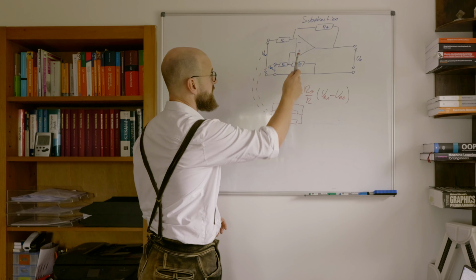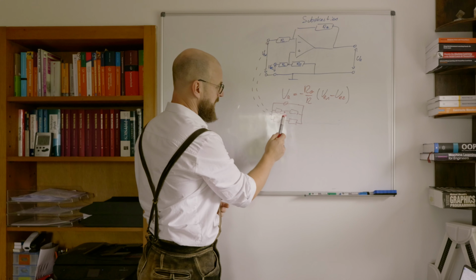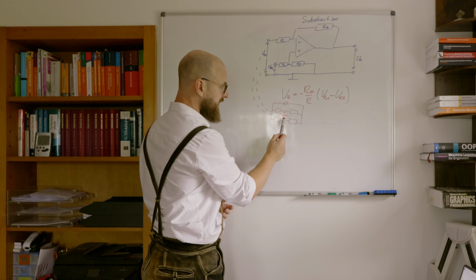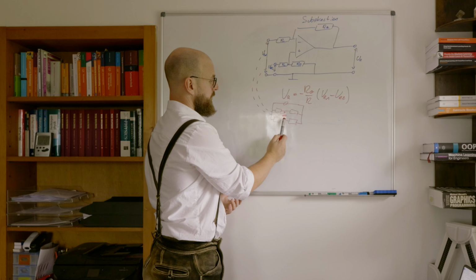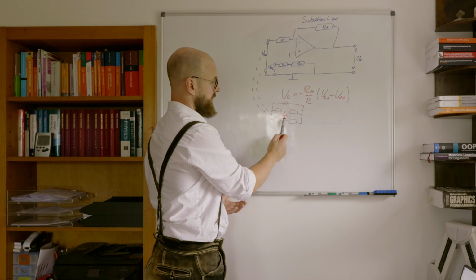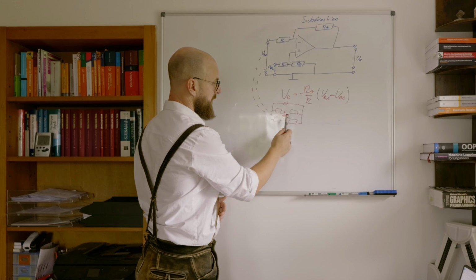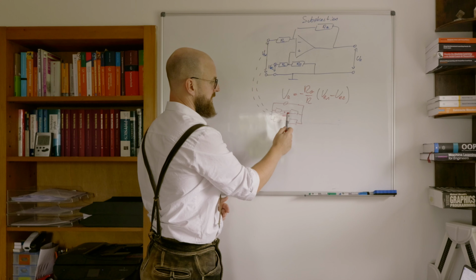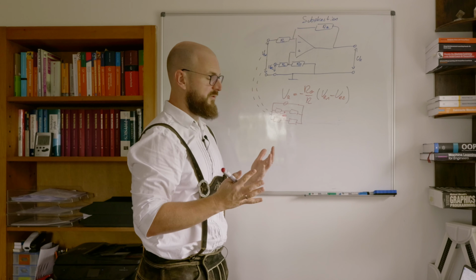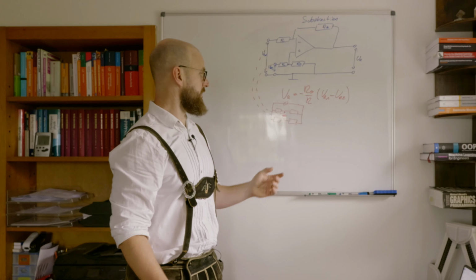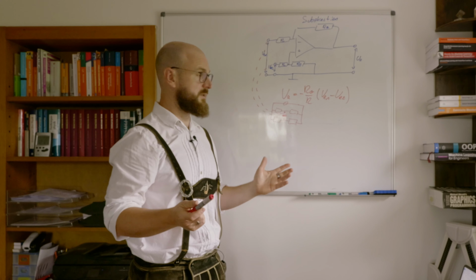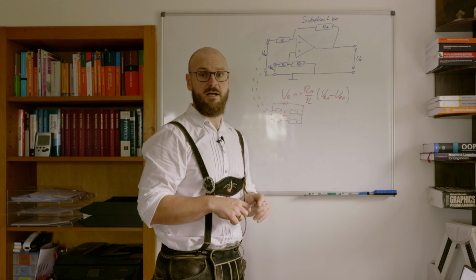But when you use that subtraction amplifier, we can just take that potential, that voltage relative to the ground, and that voltage relative to the ground, and subtract them from each other. So we get the differential voltage between those two connectors. So that's the reason for subtraction amplifiers.